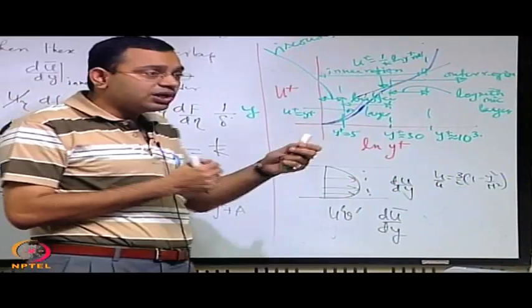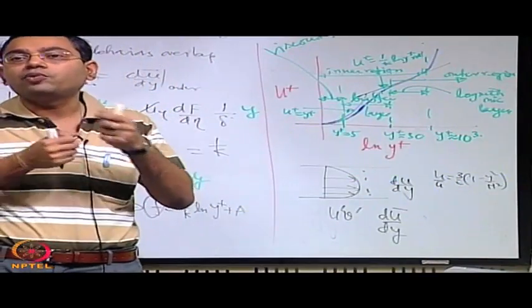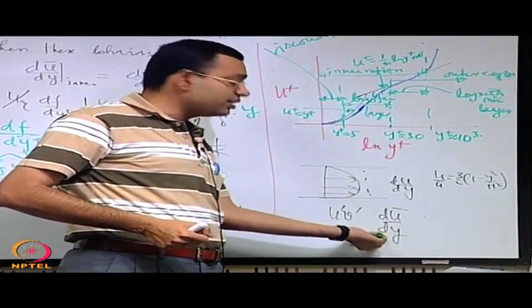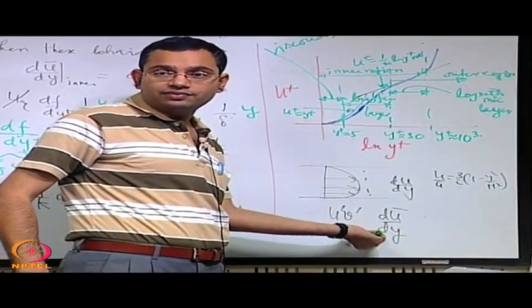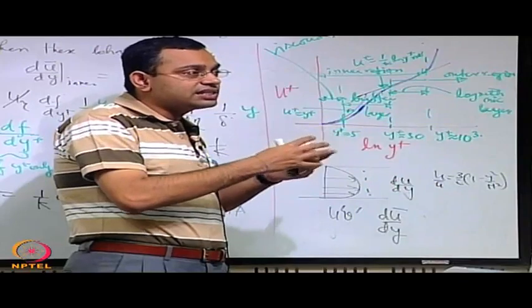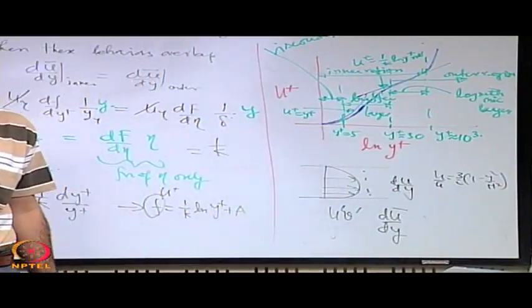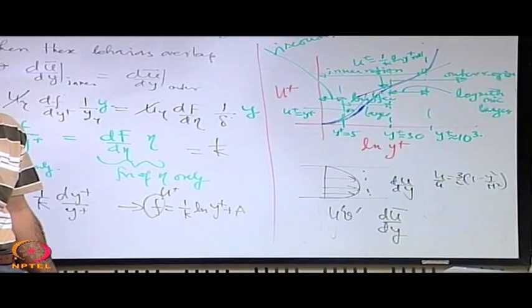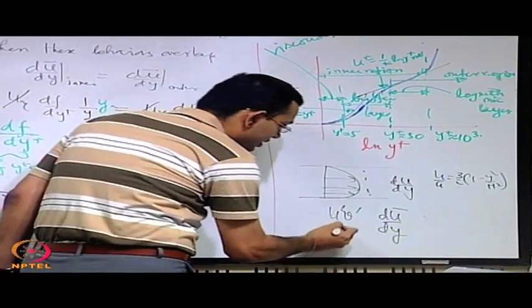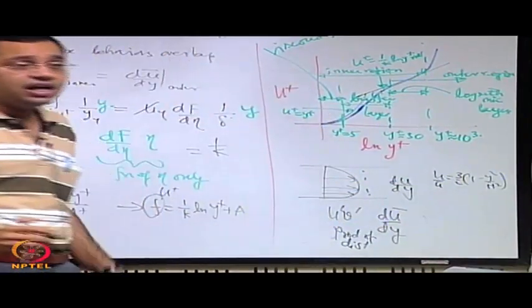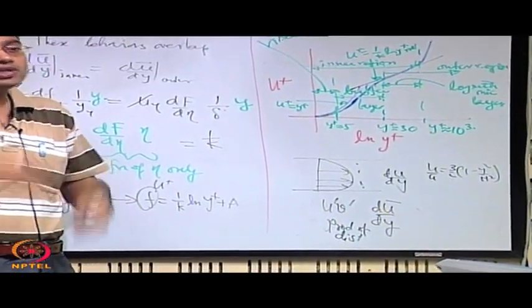It is fundamentally a transfer of momentum between these fluctuating components and the mean gradient because of shear, and because of this exchange there is a production of disturbance energy. On top of that there is a dissipation of disturbance energy, that is also by viscosity.